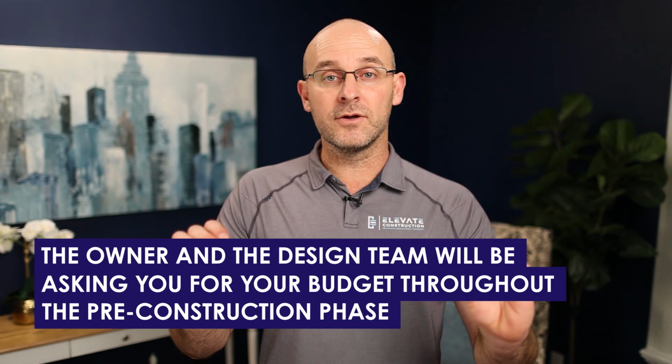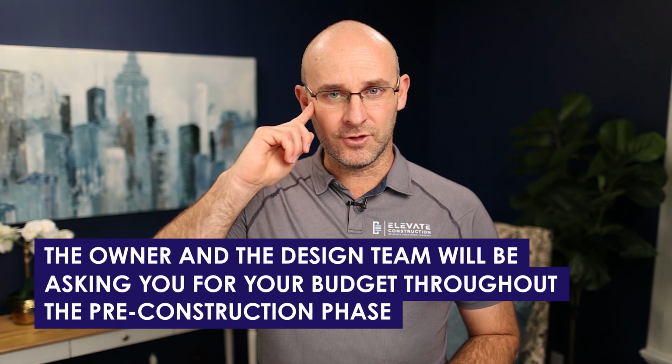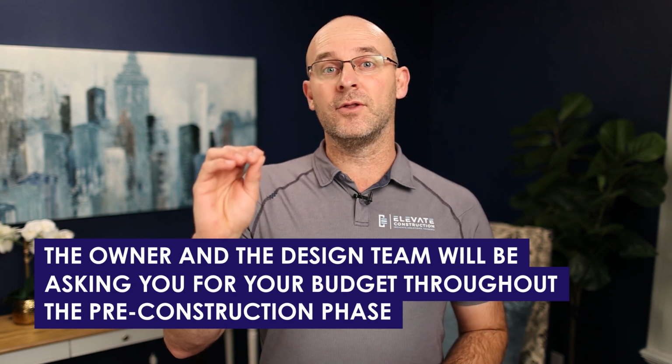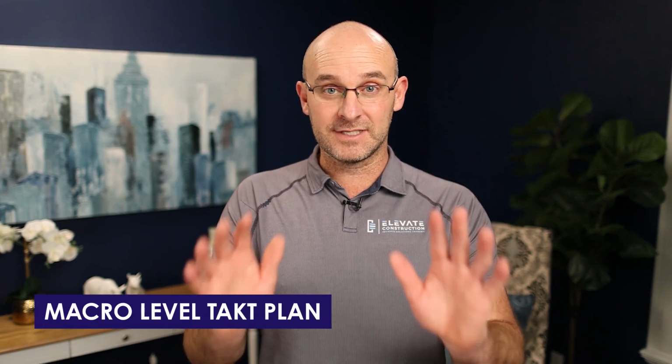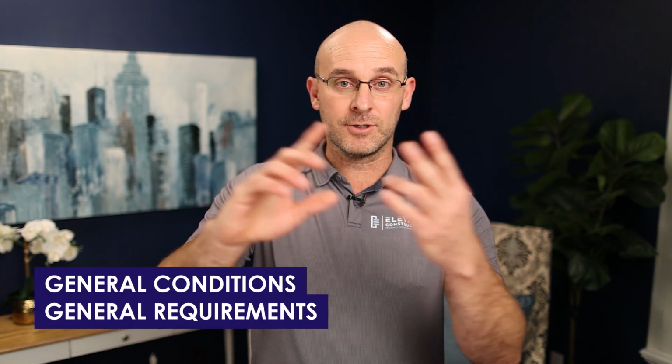Here's what I mean. The owner and the design team will be asking you for your budget throughout the pre-construction phase. And if you undercut that budget, most of the time, your owner and your designers will start to fixate on that number. So I always say, in the conceptual design phase, schematic design phase, maybe even early design development phase, we want to have a macro level TAC plan that establishes an overall total project duration so that we can get really good numbers for our general conditions, our general requirements, loop those into the budget, and make sure that our budget from day one is starting to reflect an accurate total cost for the project.